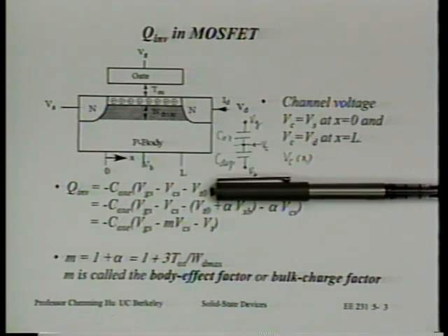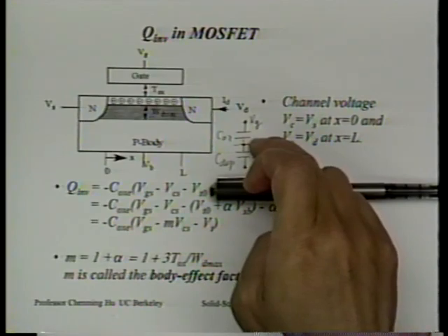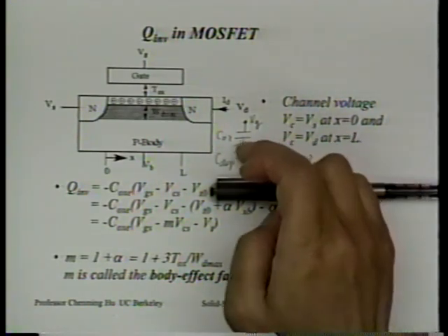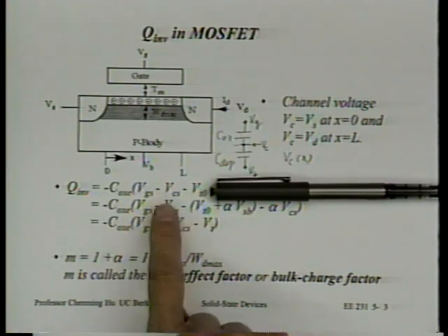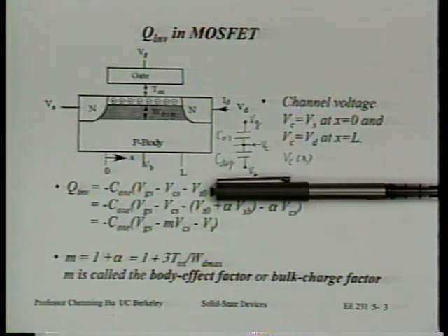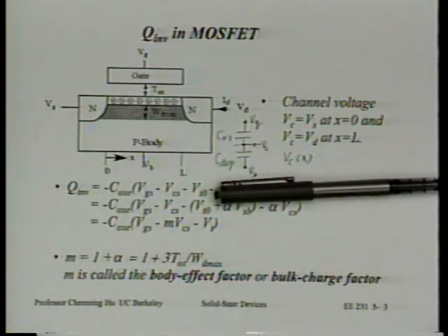That makes sense, right? The charge on this inversion layer should be proportional to, or equal to, Cox times Vg minus Vc. That's what the first 2 terms are about, Vg minus Vc. Now, what about minus Vt? Well, minus Vt is because this capacitor has an offset. We have talked about Q equal to Cox times Vg minus Vt. We have seen that before. Is that right?